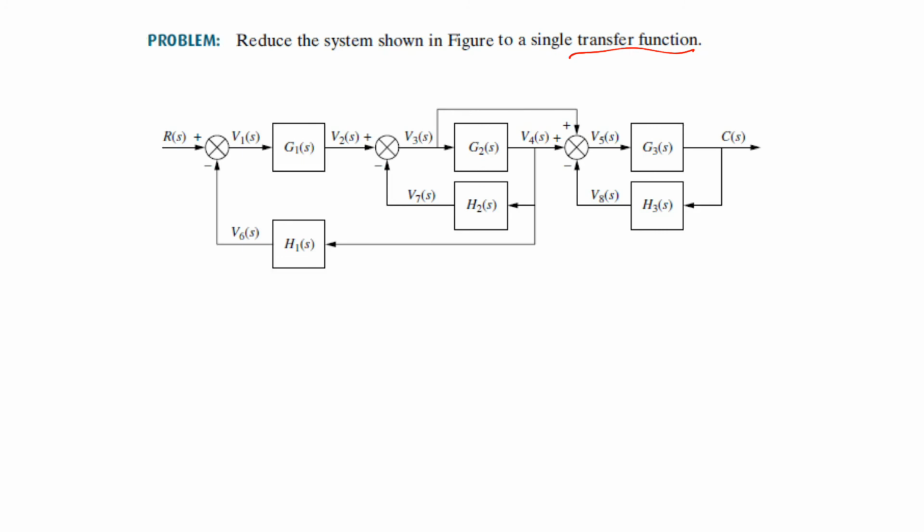Now from this we will see that there are different ways to do that. It depends upon the thinking of every individual who is doing that. So here we can say that in this case, this seems to be the feedback form. So we can calculate the transfer function of this feedback form. We can bifurcate this summing junction into two junctions, and we can get the transfer function of this feedback form.